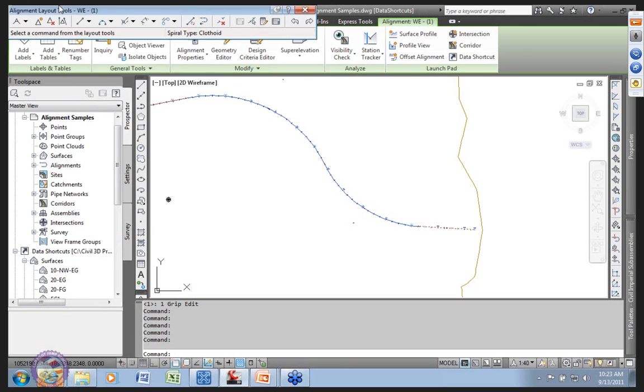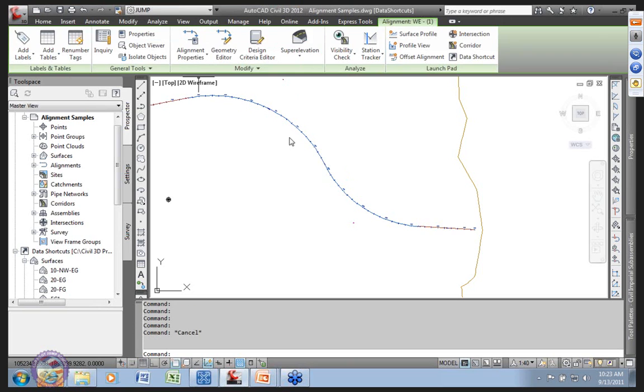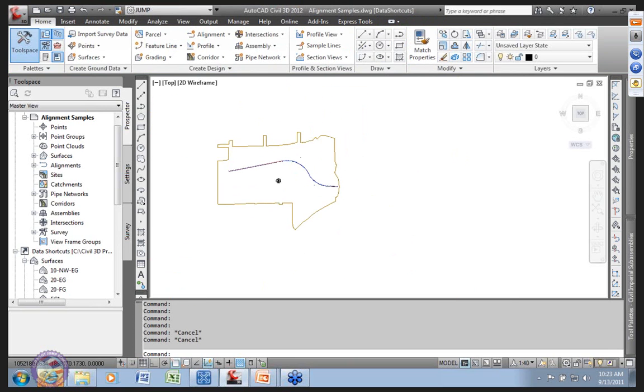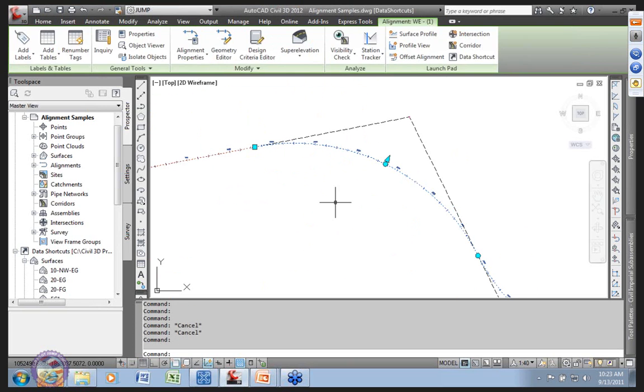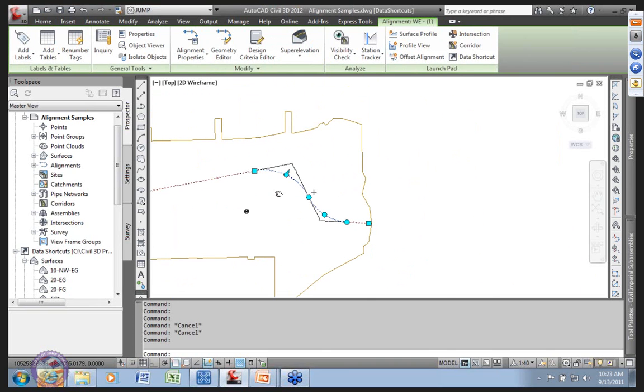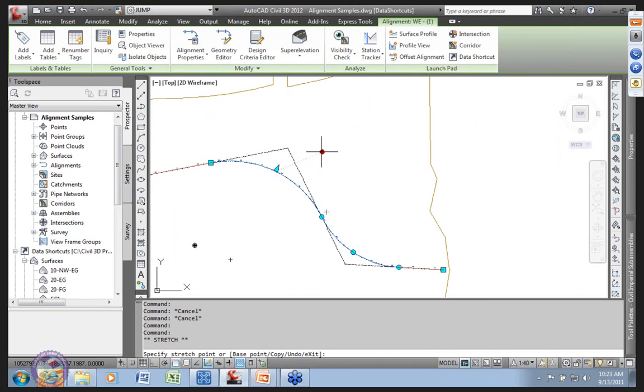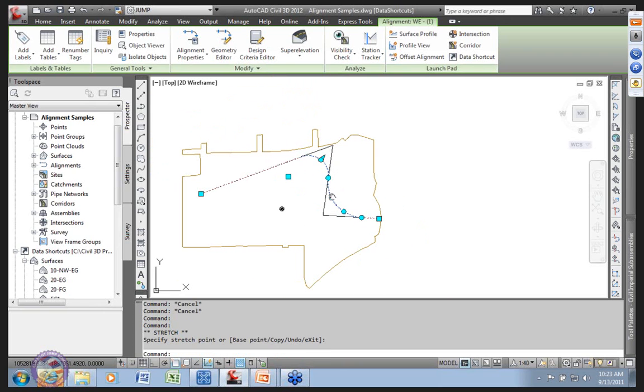Okay, and so we're going to get out of the layout toolbar, and there are undos for each one of those events up here that are separate from the whole AutoCAD undo, right? So, you know, oops, I didn't mean to do that. So you can play with stuff, right? And now our alignment has got some different constraints to it. So if now I want to yank things around, you will see that they are now all tied together and remain tied together by what's going on.